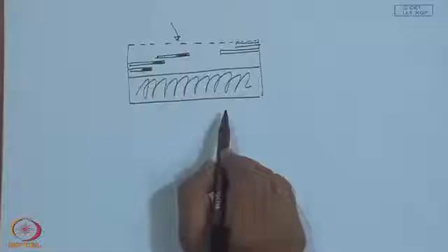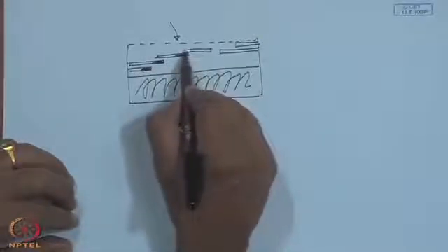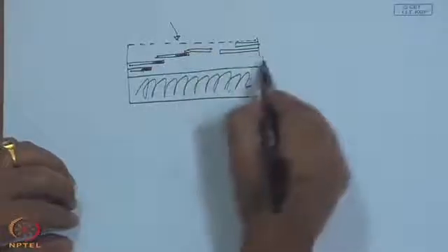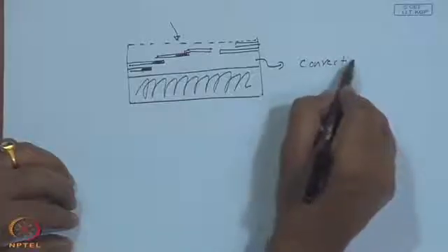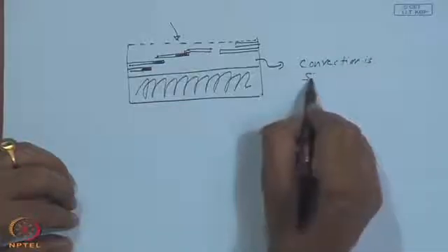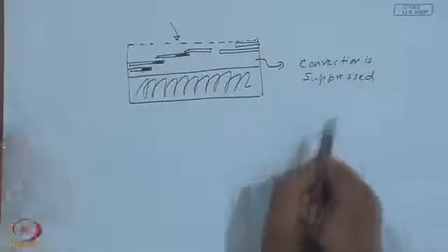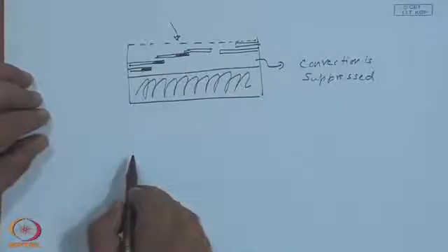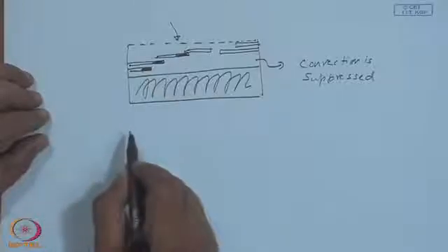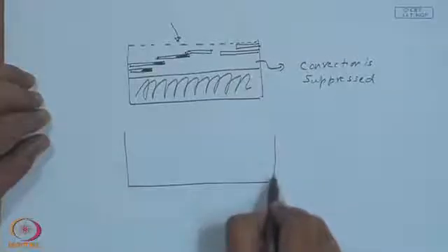And this achieves it because you have got a large number of baffles, you may call it, so convection is suppressed. Consequently, your top loss coefficient will be lower. And now, this is another matrix arrangement. It is somewhat similar in idea.